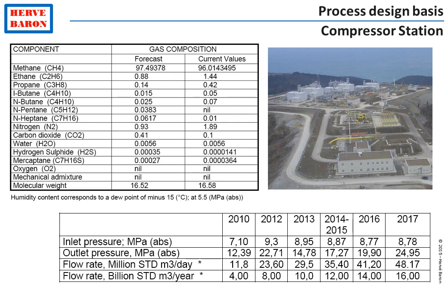For the case of oil and gas facilities, the feedstock, which is usually reservoir effluent, varies in flow and composition over the years due to the depletion of the reservoir. Therefore, a range and envelope of composition and flow is defined in the design basis. In addition, not only the maximum capacity is defined, but also the minimum capacity, what is called turn down.